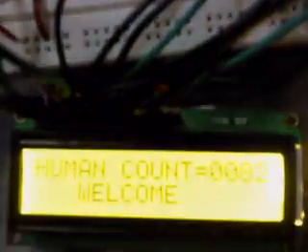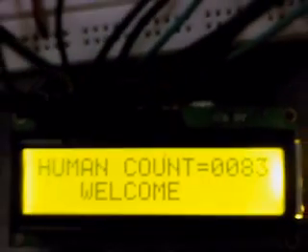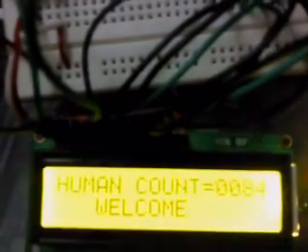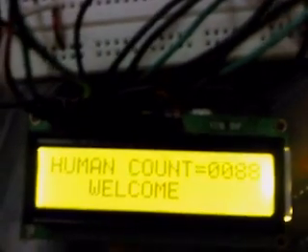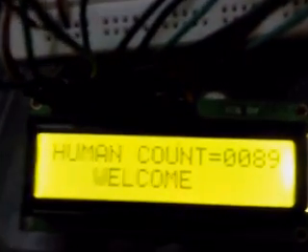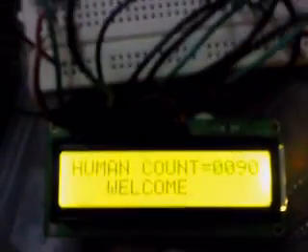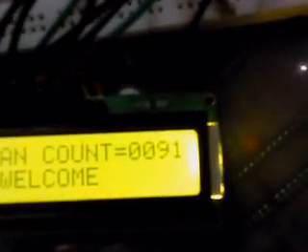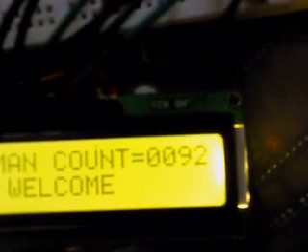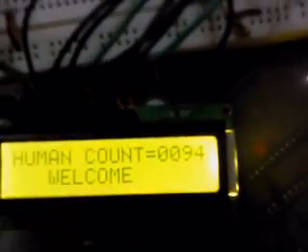And this is the 8-bit register of the LCD display from 0 to 7, and I am assigning the first port of the microcontroller fully to the LCD, so that 8-bit data can be sent. So this is sending the 8-bit data in this way, so that I can count this 91, 92, 93 and so on. So this is a simple circuit I have made here.